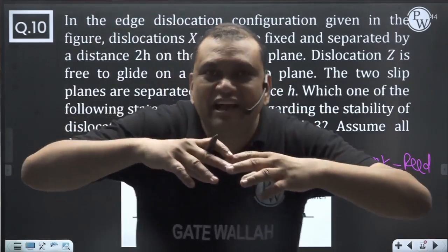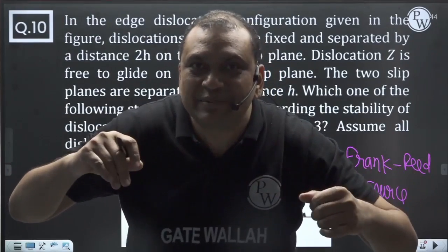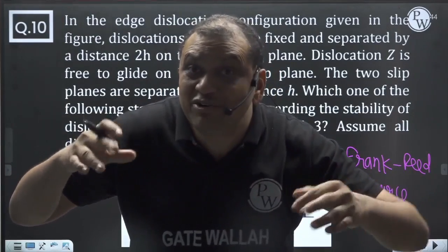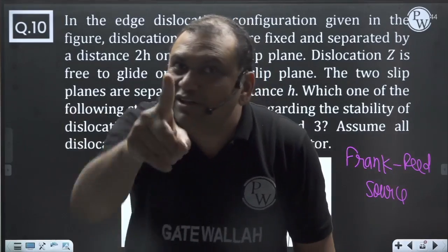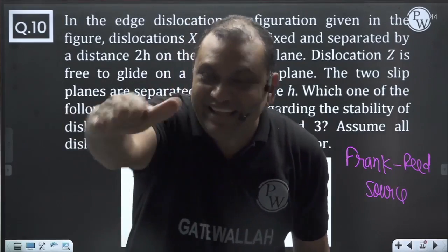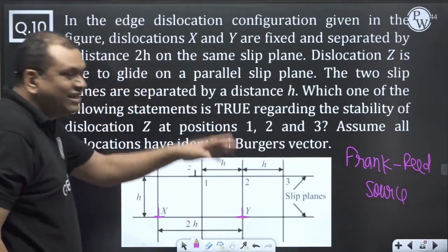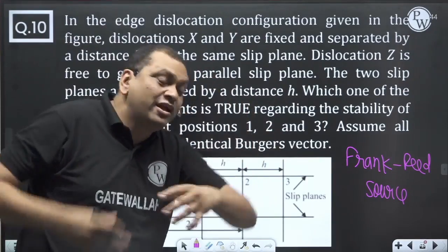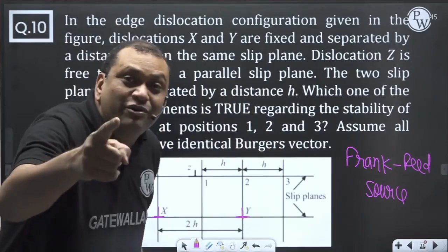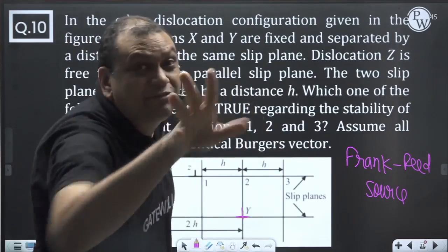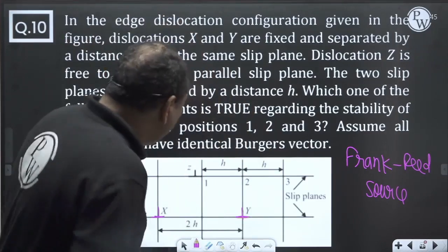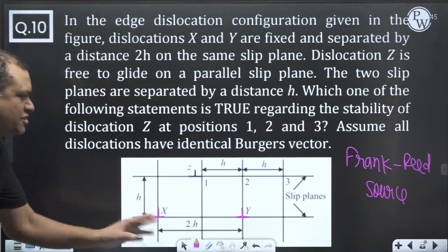The number of dislocations multiplies. The new dislocations that are coming up do not move. In the theory class, we will discuss these things separately. So these X and Y are the dislocations that are not moving. Probably these are the dislocations generated by the Frank-Read source.